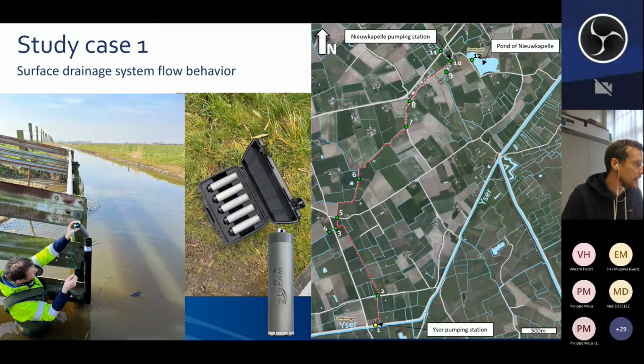As you can see on the left, the fluorometers were installed in black PVC pipes to avoid daylight influence and to ensure a stable and safe location, because we wanted to repeat the operation. In total, we made 3 dye injections with sodium fluorescein and with the same field configuration. We had different gradients and discharge conditions to test the same dye tracing procedure.